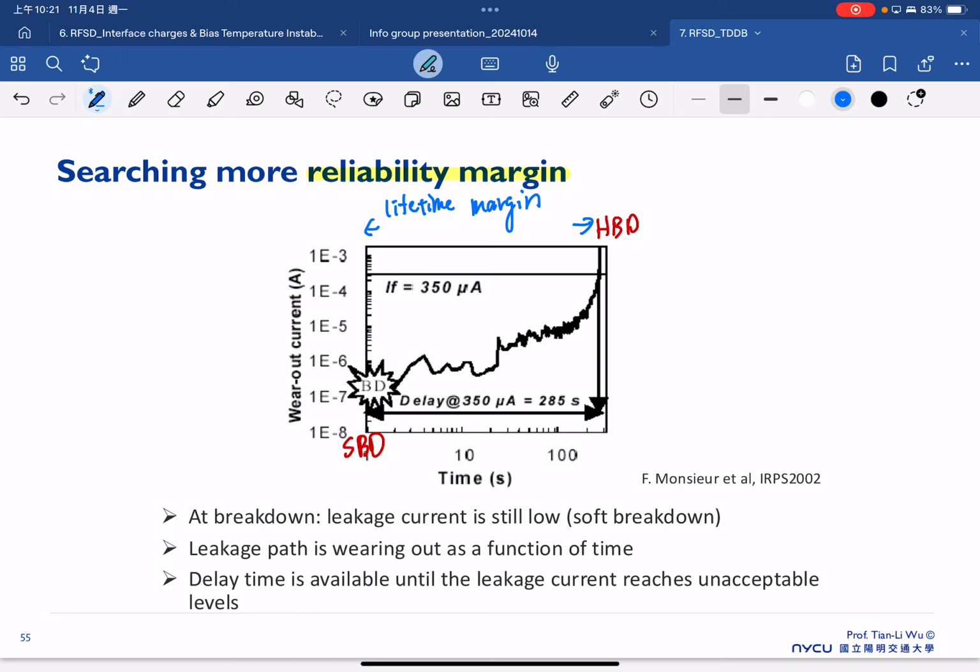If we look at our device characteristic during operation and see the noise in our current, this gives us a very useful warning that our device can probably only operate for another 100 seconds, or another 1000 seconds, and we should stop using this device because otherwise the completely destructive breakdown will come very soon.